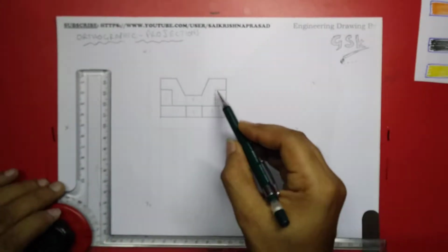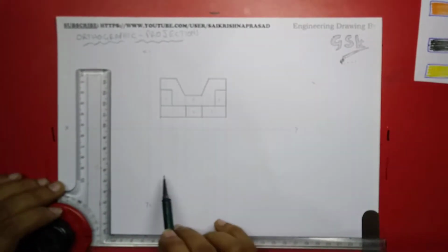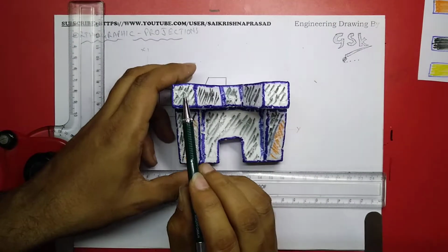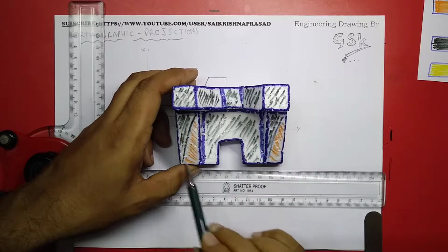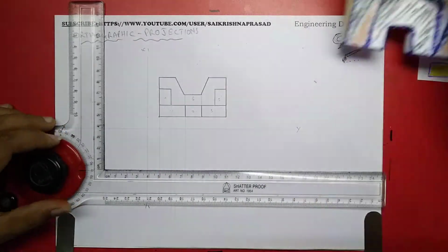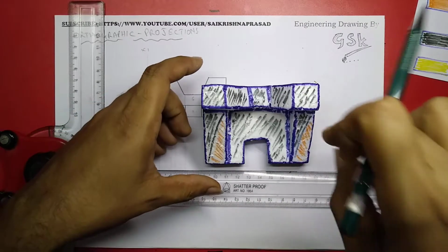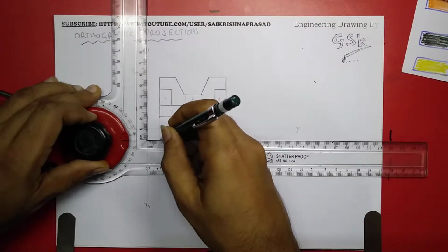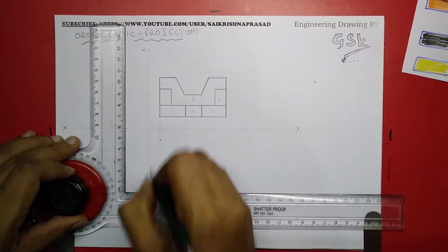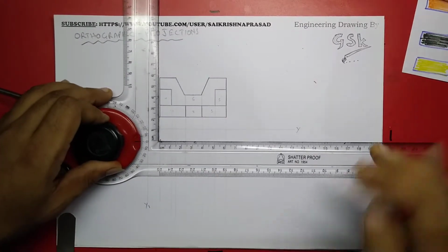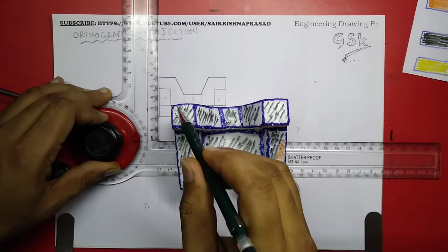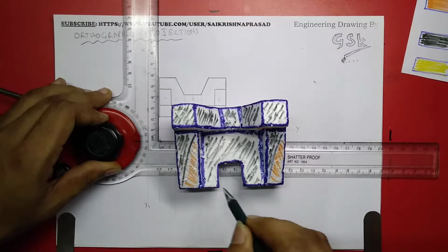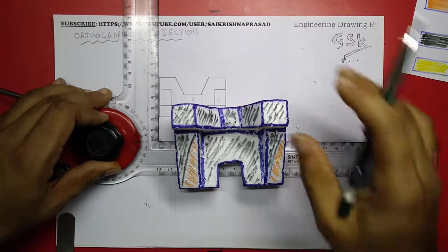I think we have finished the drawing from each and every corner. There's a projector line. Now coming to the top view, we can see this, and all these surfaces. So the width, looking from top, is 35. So same here, I'll take 1 centimeter gap over here, and I'll start the figure from here. Looking in this direction, I can see this whole line, and here also I can see this whole line, but here coming to length I have this gap.